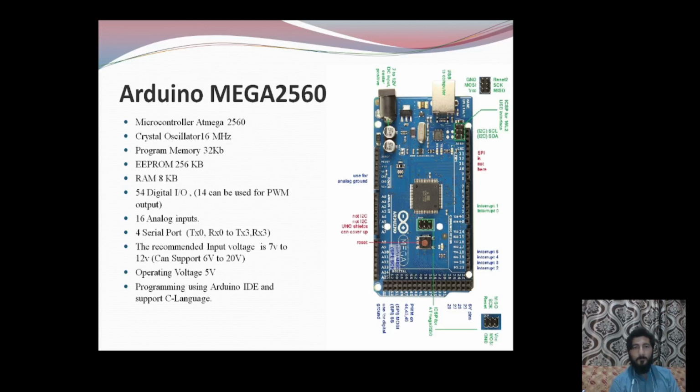From these tables, these charts, from this presentation, I hope you will be able to choose which Arduino is more suitable. If you need a lot of hardware interfaces, if you have a great need of IOs, then I recommend you use Arduino Mega. If you have fewer IOs, then use Uno or Nano.